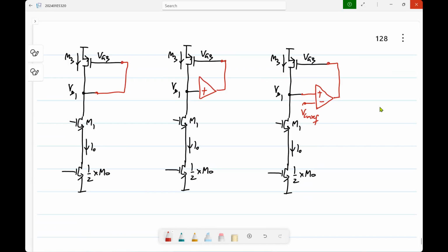No. We don't know what VCM we want. We have not defined it. Right now, it is enough if all transistors remain in the saturation region. So any circuit that does that will be fine. And then, of course, the circuit we follow this up with may put some more constraints on VD1. But right now, if we do this, what will be the VG3? It will be VDD minus VSG of that. Because this is diode connected, and assuming VICM is sufficiently low, this will for sure keep all the transistors in the saturation region, right? So that will work.